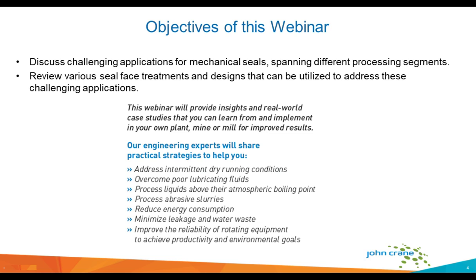During industrial processing operations, every mechanical seal application experiences its own unique set of challenges, including inadequate seal face lubrication, high heat generation, and dry running conditions. These issues can cause leakage, unplanned equipment downtime, and even catastrophic equipment failure, negatively impacting operations and profitability. Mean time between repair intervals for mechanical shaft seals can occur frequently in these harsh conditions, which means maintenance costs go up and equipment runtime goes down.